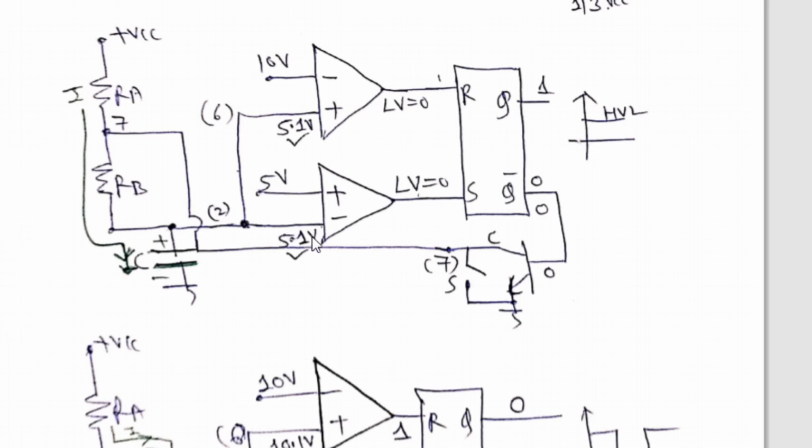So capacitor will go on further charging from 5.1 volt to 6.1 volt, 7.1 volt, 8.1 volt. Like that, capacitor will just cross the two-third of Vcc, 10 volt. So the moment the capacitor just reaches two-third of Vcc, the entire situation changes, and that we are going to see. So remember, HVL continues from 0 volt even though the capacitor is crossing one third Vcc and it is charging towards the two third of Vcc.